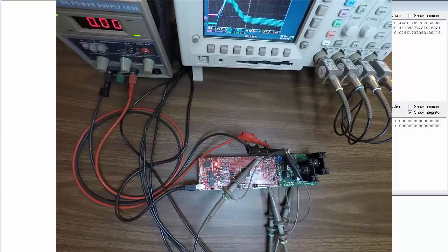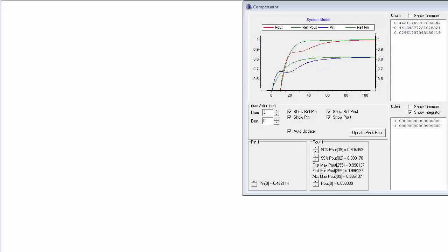In this case study, a buck power supply development kit is used as a platform for an example buck converter. A bench supply provides bulk power to the kit at 9.2 volts with a 3 amp current limit. The buck supply regulates the output at 2.0 volts into a test load. The first task is to characterize the plant in the system.